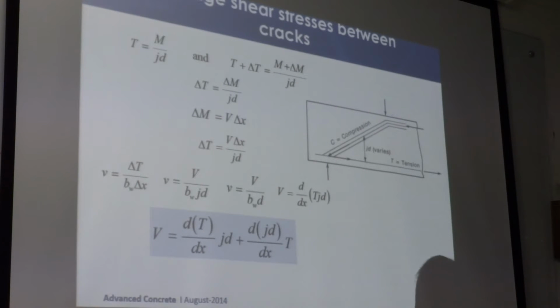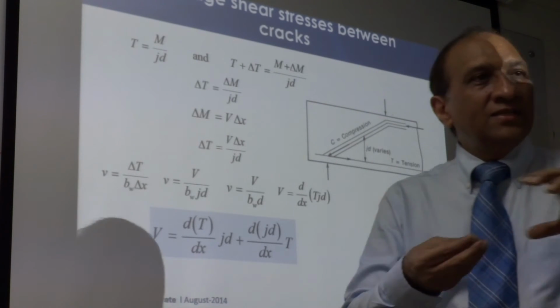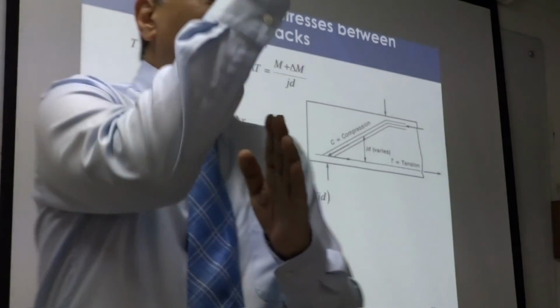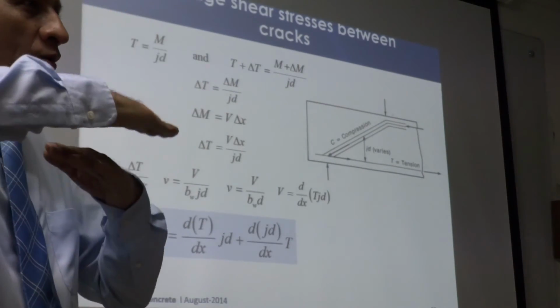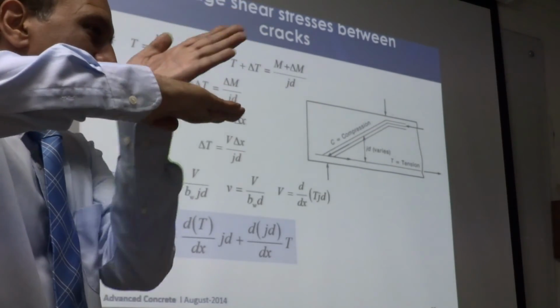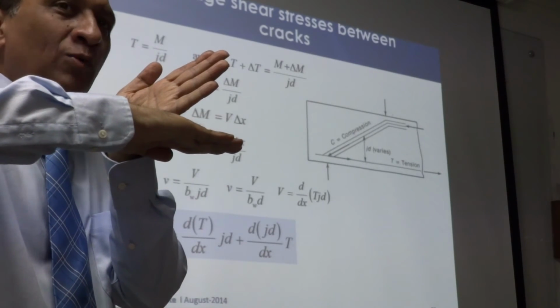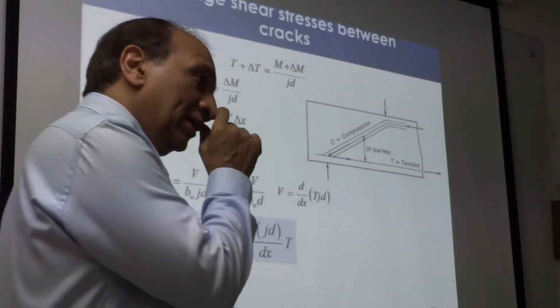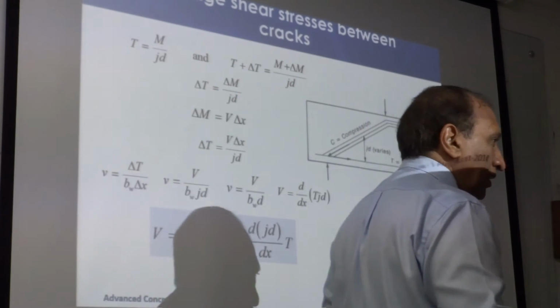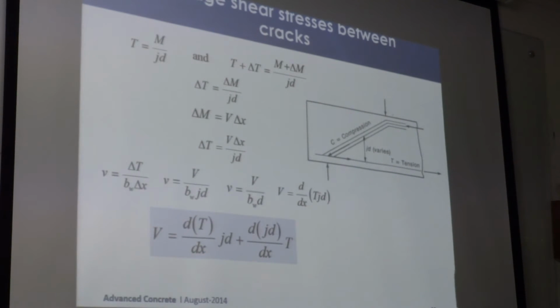because, like I mentioned, it provides us the tension. So whether we provide the reinforcement vertically or horizontally, it will always have a component diagonally, right? That means shear reinforcement can be horizontal or vertical. It has some contribution, and that is what we will study when we talk about walls and beams.